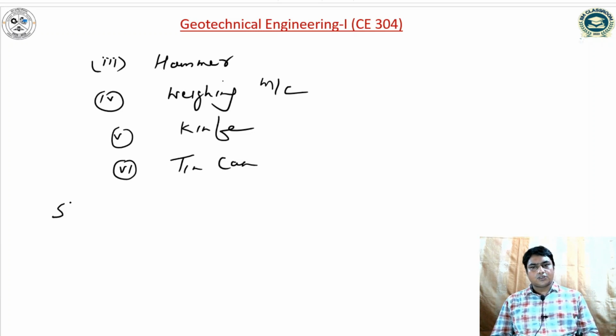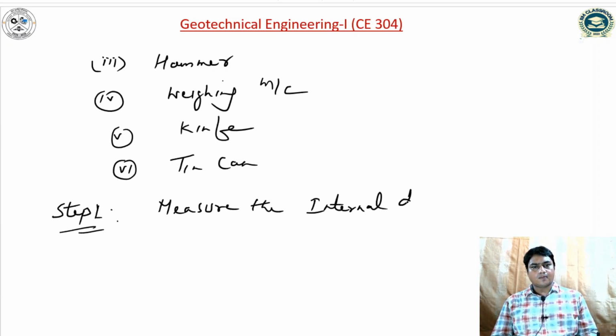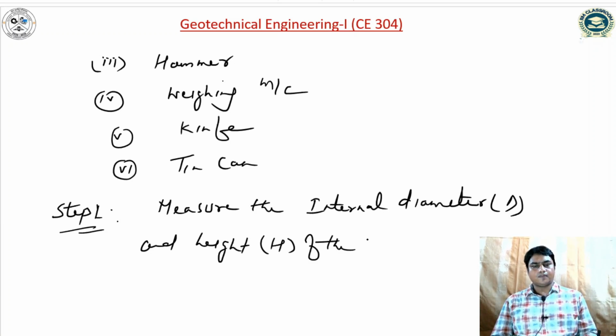So step first, if I write the procedure: measure the internal diameter D and height H of the cylindrical core cutter.